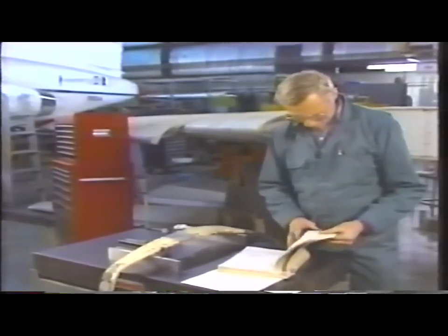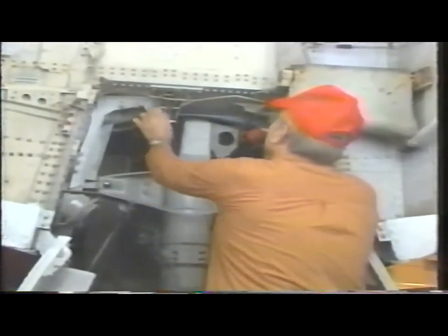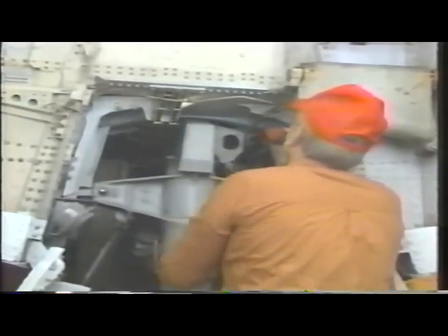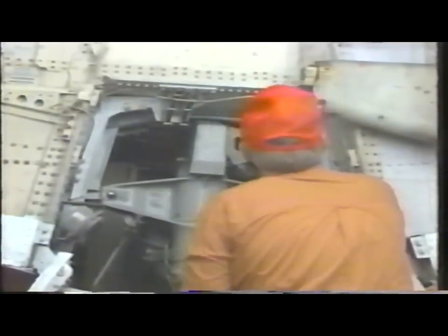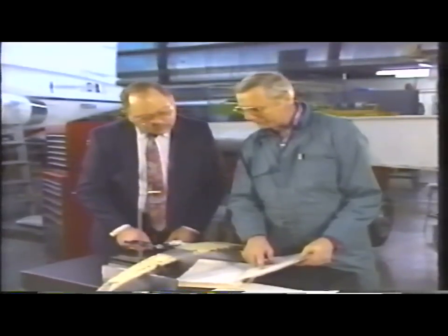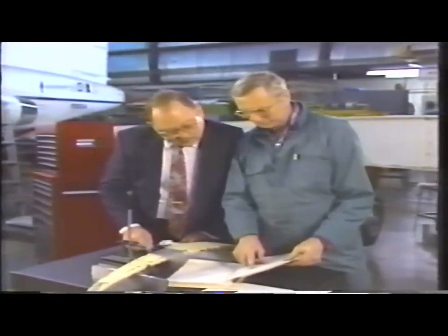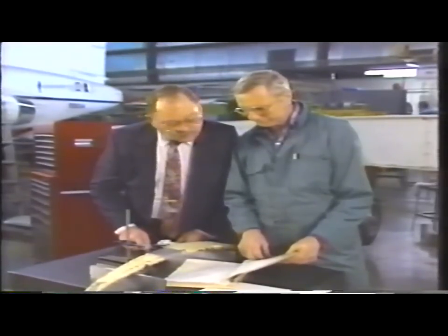replaced. On large structural parts, where the corrosion damage exceeds what is allowed in the structural repair manual and replacement isn't practical, contact the aircraft manufacturer. Corrosion damage not outlined in the aircraft structural repair manual will require FAA engineering or manufacturer's data to repair the component.